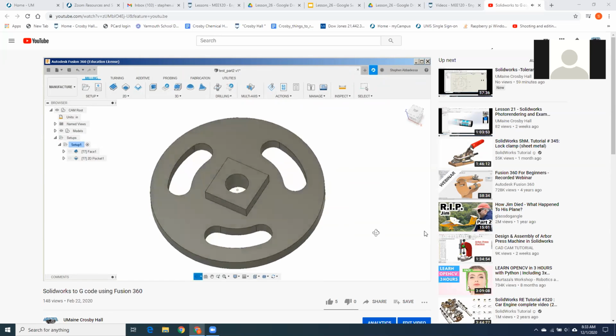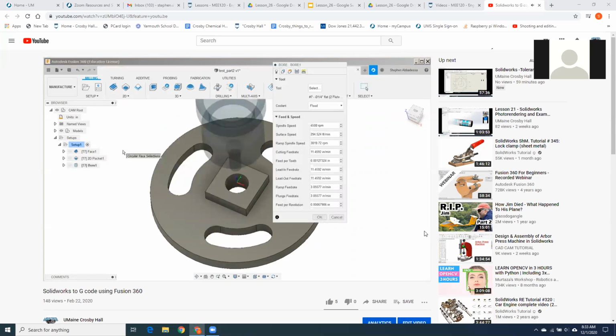So now let's do the center bore. We're assuming a 1/4 inch end mill. This is a 1/2 inch hole. What we can do is we can orbit that tool around, just spin it right down in, and create any size hole we want that is greater than a 1/4 inch. Let's do that. We'll say 2D, bore, so that means go drill a hole with the end mill. First one looks good, 1/4 inch end mill, 4500 RPM.